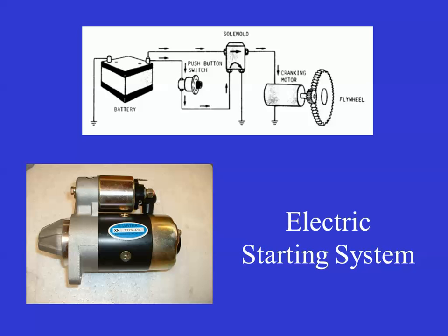Now you're only cranking for maybe 30 or 60 seconds. In fact, if you crank the starter on your car for too long a period, you will melt the starter down. They are not designed to run for more than about 15 to 30 seconds. And if you crank your engine over and it's not starting, then you need to wait. Crank it for 15 seconds, then wait 4 or 5 minutes and crank it again. Don't just keep cranking because you will melt the starter motor down. I've seen that happen.